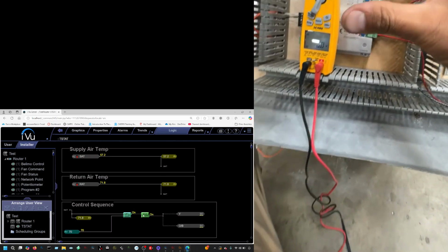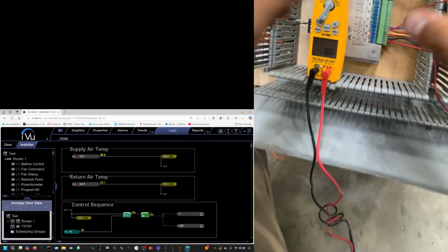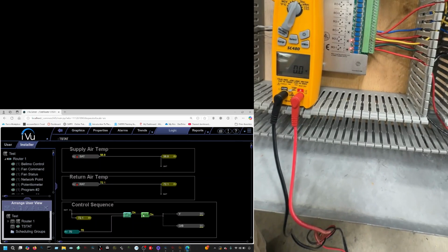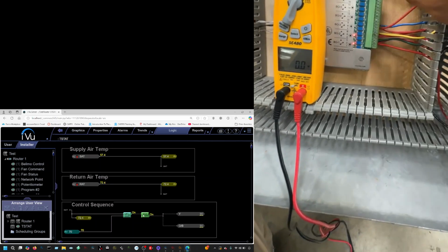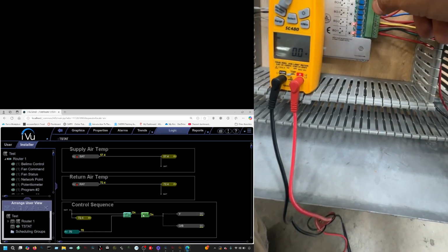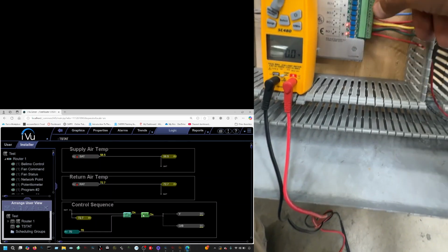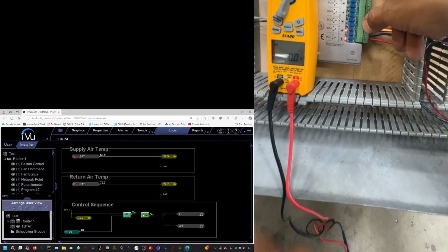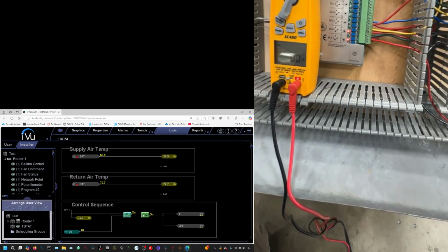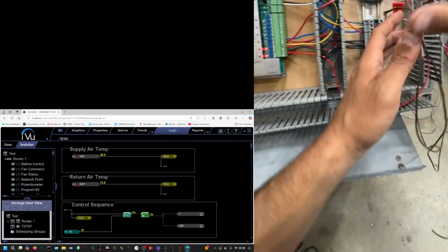Typically, in a building automation controller, sometimes you have your inputs on one side, your outputs on this side. This specific one, though, you have your analog inputs and binary inputs here. You have your analog outputs here, and then you have your binary outputs. So analog outputs, binary outputs. And this is essentially just switches. And then right here, you would use this for economizer, cooling and heating, like actuators that receive 2 to 10 volts DC signal right here. And then the wiring, yeah, it's a mess.